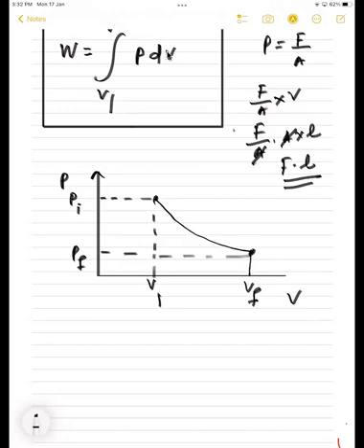So work done, students, see here: internal energy, heat and work depend on the path followed to reach the final state. But the work done by the gas in expansion, see here, the volume is increasing. Initial volume was at this point, then final volume. Volume is increasing, that means expansion is taking place now. Yes or no? So work done by expansion from initial state to final state.